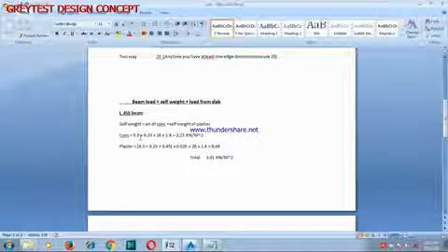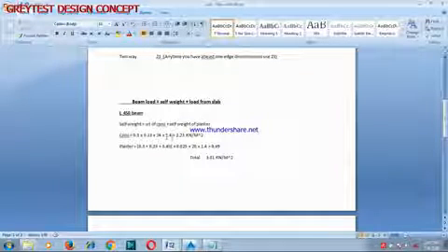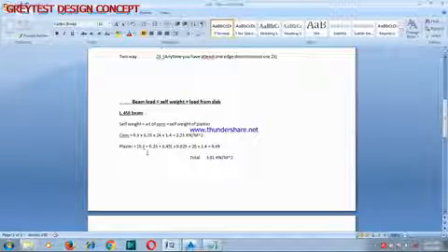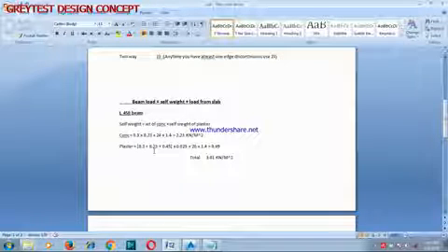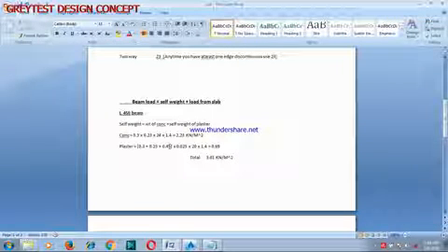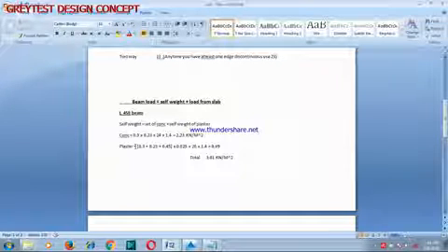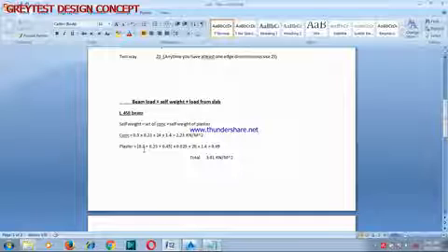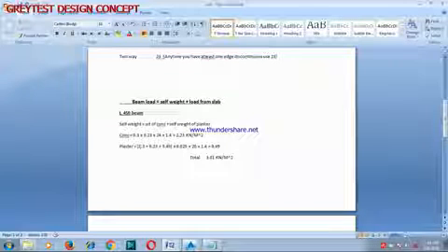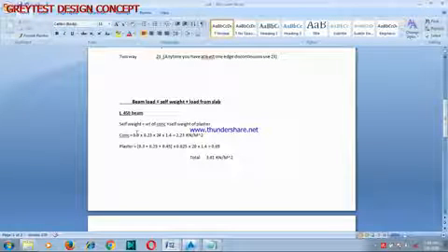Now you can see this is 300 by 230 by 24, which is the density of concrete, multiplied by the factor of safety. Okay, look at this plaster, which is 300 by 230 by 450. Now if it's a 600 beam, definitely this value is going to change. For a 600 beam, your bottom depth is going to change. It will definitely no longer be 300. Okay, you need to take note of that.